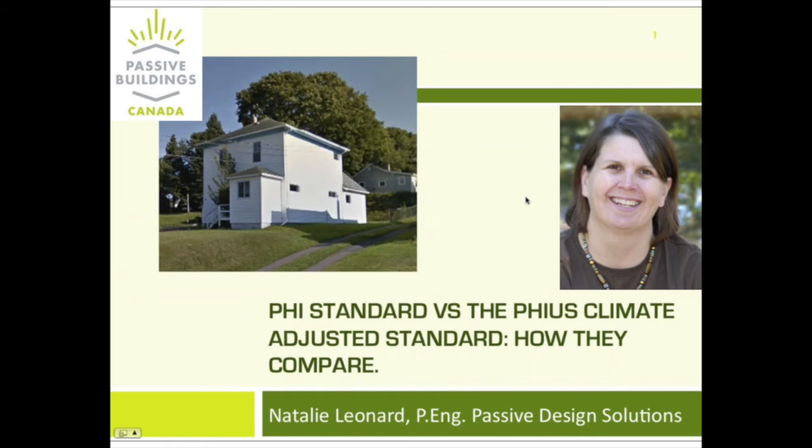There's actually a resource on the PHIUS website. Somewhere in there's like tools and resources, and there's a spreadsheet that PHIUS put together, which has been extremely valuable in making the energy modeling discipline, but also in evaluating which units to look at. What they did was, a lot of Canadian HRVs were going to dump the waste heat from inefficient fans into the supply air, thus bumping up the sensible recovery efficiency numbers, but the electrical use is really high.